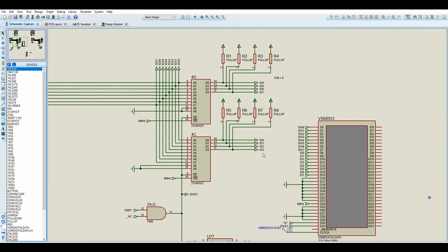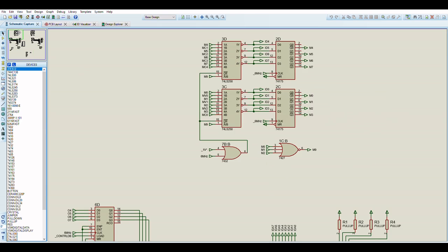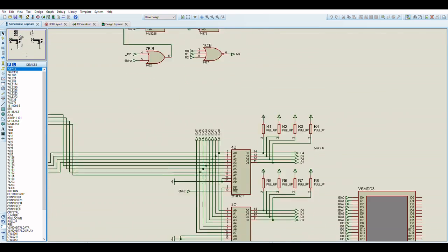It means that there isn't really much special detection logic needed, and the weak pull-ups help to reduce the complexity of the signals coming out of or going into the RAMs. The RAMs will pull down from the weak pull-ups, so the values are not really affected.